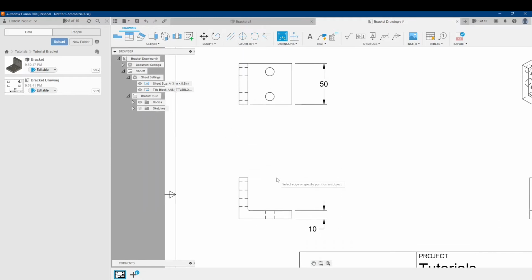Oh, and another thing too is add dimensions where what they're telling you the size is really obvious. So I want to say how long this is, from here to here. But it's not really obvious looking at this, because you have this bit in the way and this fillet here, which isn't really conveyed. You don't really know that until you hover over here. It says 47.5 millimeters. So, yeah, and then you're like, why is it 47.5 millimeters there? That's because you can't tell there's this fillet right here. So, do it here. Click on that.